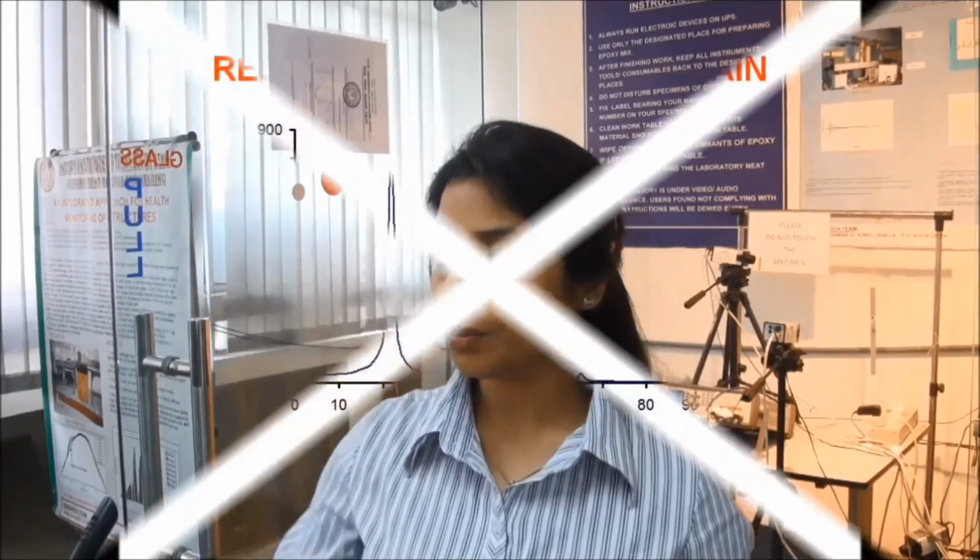Now this is a typical response of a piezoelectric patch, which is either surface bonded or embedded on a host structure. The structure may be RC structure or a steel structure. So this is the voltage response in time domain. So you can see when this response is particularly when the host structure is hit with an impact force. So initially the response is very high, then due to damping it slowly dies down.